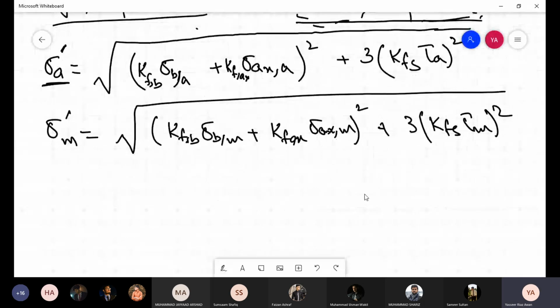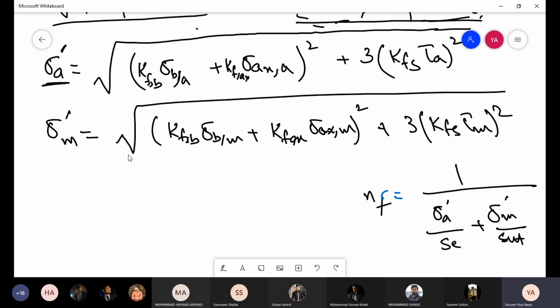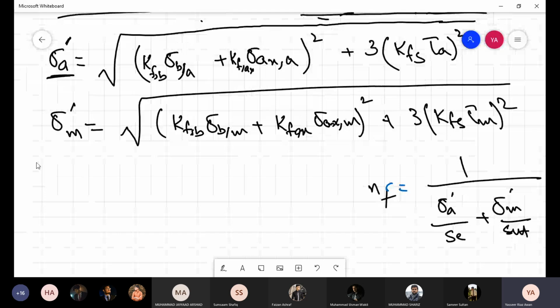And we use that. The rest of the procedure is the same as it was for pure loading cases. So for example, if we are using the modified Goodman diagram, we use sigma a prime divided by Se plus sigma m prime divided by Sut, for finding the fatigue safety factor for infinite life, okay. A couple of differences will come up, but this is very easy.